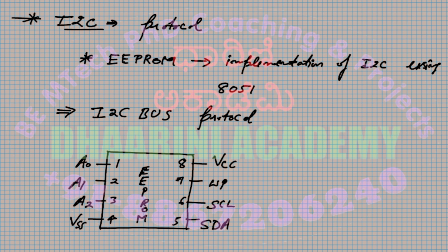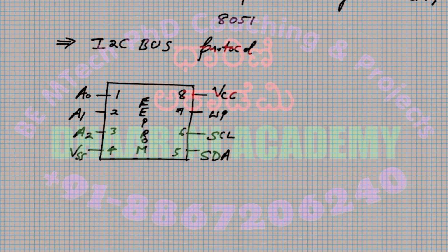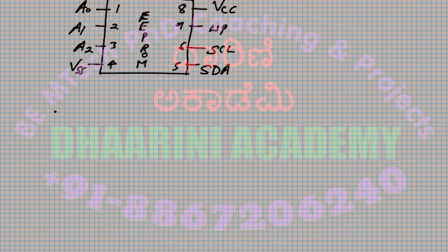Okay, let's look at the fundamental characteristics of the EEPROM. Inside you have 8 blocks of memory, and each block is 8k, that is, kilobits. So totally 8 into 8k, you have 64 kilobits. That's the measurement, that's the size.